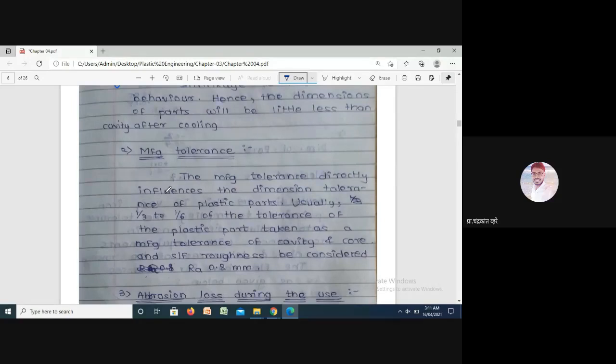In such cases, we need to finish that shaft because we are fitting the bearing on it. For such cases, you must keep some 1 mm or 0.5 mm of diameter.